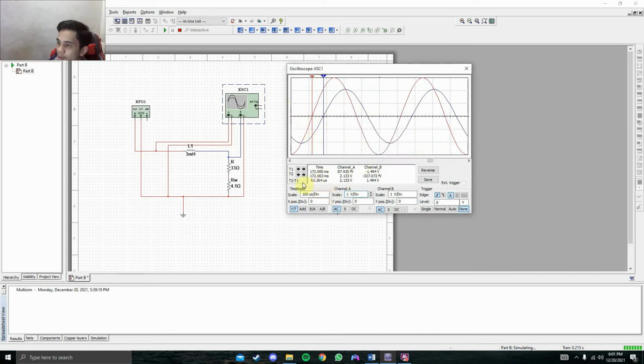Then select a trace for channel B, AC, then set the Y value again to 0. So we get here that Y, the difference between the two signals, is 63.264 microsecond, T2 minus T1, and then the period, 1 cycle, 1 box, 2, 3, 4, 5, same box, plus here is 5 boxes, and then times it with the scale of 100 microsecond per division, equal to 500 microseconds.